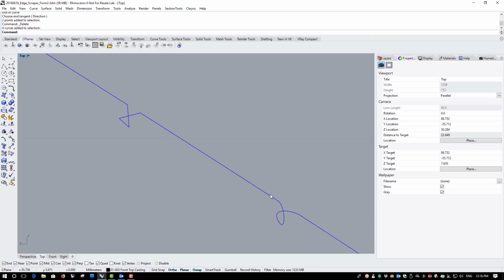This, in the case of a NURBS surface down here, would be where there is a loop in the edge that self-intersects, so the surface, rather than being a continuous description, actually intersects over itself. Therefore we have a volume inside here plus the larger volume, and sometimes you may see the mesh equivalent of this, where the mesh has not built correctly and some faces have collapsed inside of the volume.